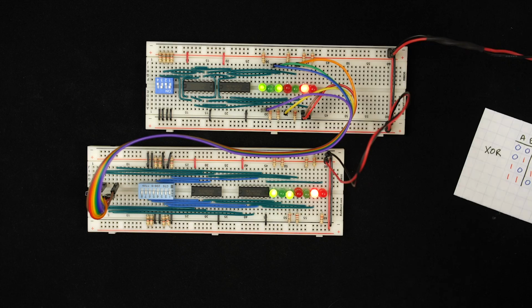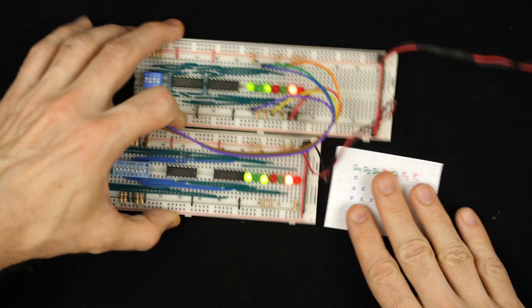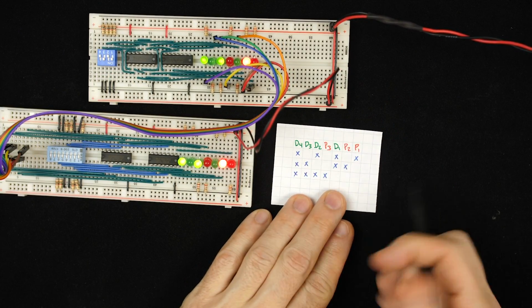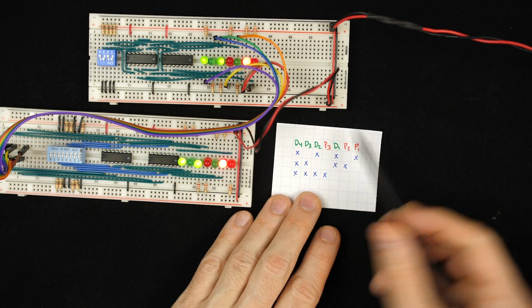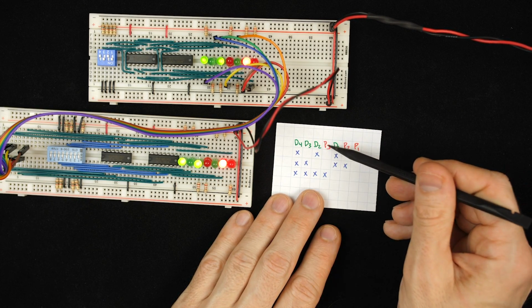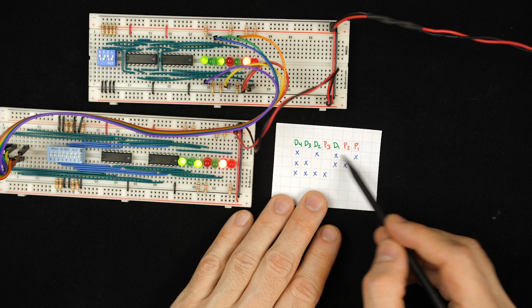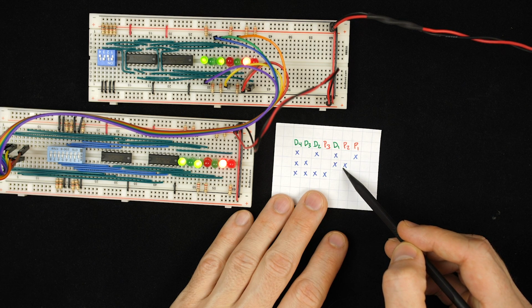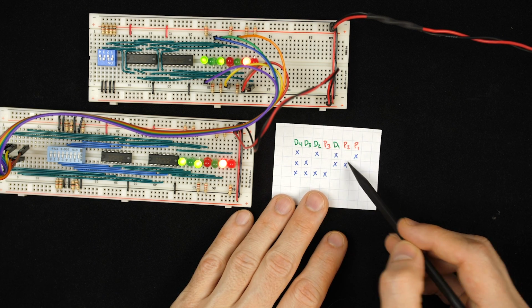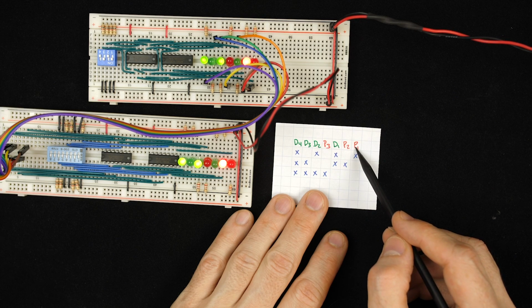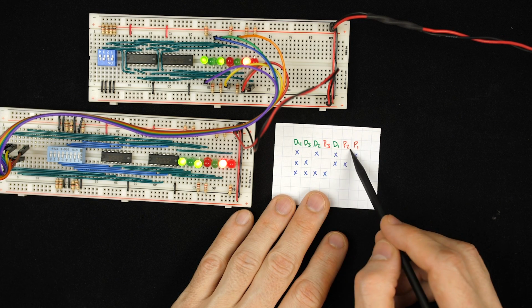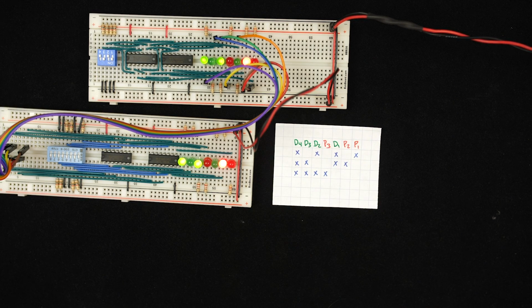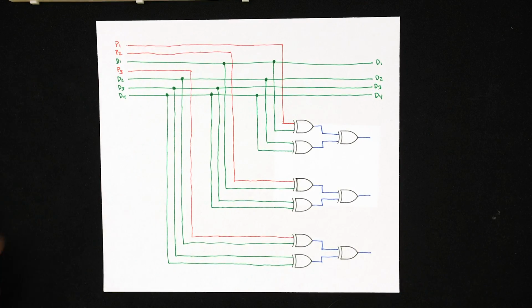And the way the error correction is going to work is we want to basically compute each of these parity bits and see which of them are wrong, because it was by checking each of the 3 parity bits that we were able to determine, based on the combination of which parity bits are wrong, if any of them are, which bit was off. But we need to first compute those parity bits and figure out if any of them are incorrect. And the way to do that is more XOR gates, because XOR gates are great at computing parity.